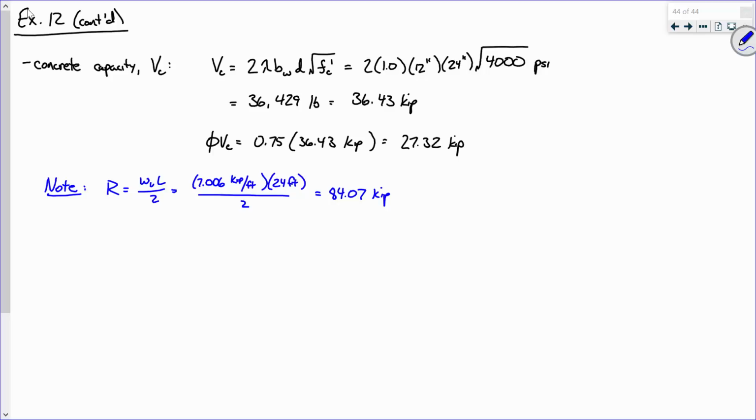All right. Now for the steel, the problem with the stirrup calculation is that there's multiple different regions. How many different regions of stirrup spacings are there for this beam? 4. Okay, so here's what I'm going to do. I'm going to do the capacity calculation for one region, and then you'll see how everything else is just repetitive.